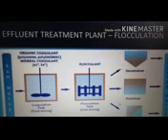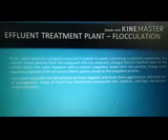When an inorganic coagulant is added to water containing a colloidal suspension, the cationic metal particles from the coagulant neutralize the negatively charged electrical double layer of the colloid. Much the same happens with an organic coagulant, except the positive charge most commonly originates from amine NH4+ groups attached to the coagulant particles.